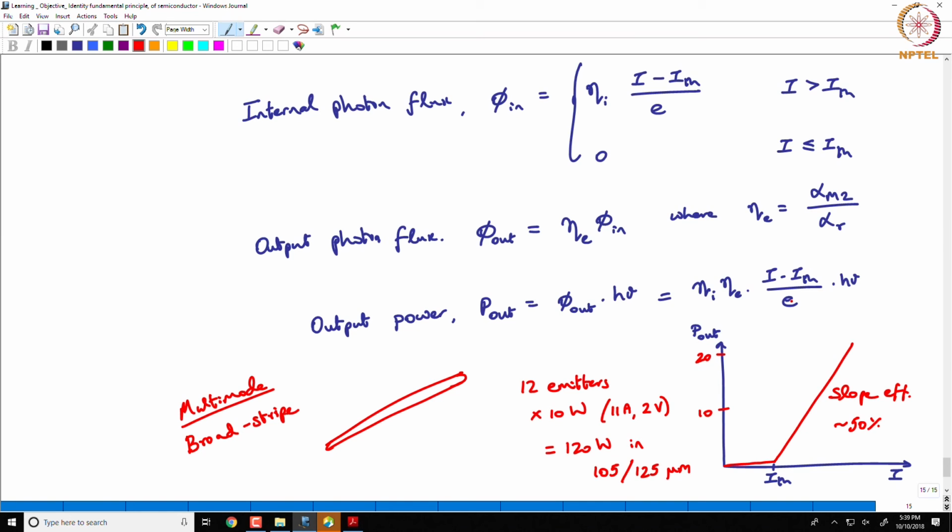But one thing maybe I will mention is there is a specific class of laser known as the DFB laser, wherein, if this is my active medium, this is my active layer, I put some perturbation along this, and let us say my perturbation is such that this capital lambda, the period of that perturbation, provides reflectivity at a particular wavelength called the Bragg wavelength.